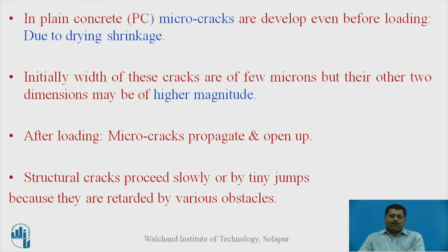Now, before loading, concrete is subjected to micro cracks. The reason is drying shrinkage. Because of drying shrinkage there will be micro cracks, and whenever these micro cracks are subjected to loading, they will open up and start to propagate also.